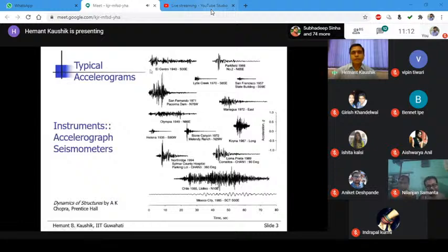Another reason that people use this earthquake very frequently in their research is that it has so much frequency content that when we analyze structures using this, it is expected that the structure will respond in a very vigorous manner, in the sense that the response will be higher. So we can check the structure for safety here easily.